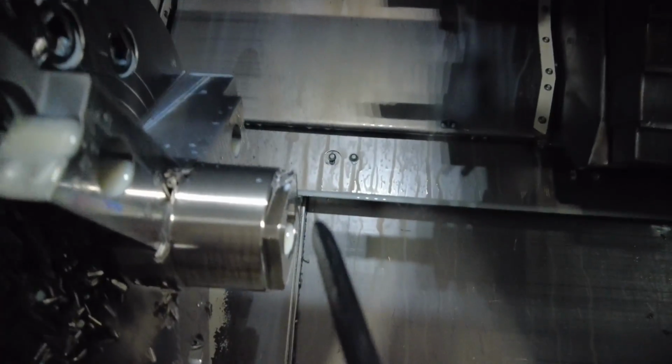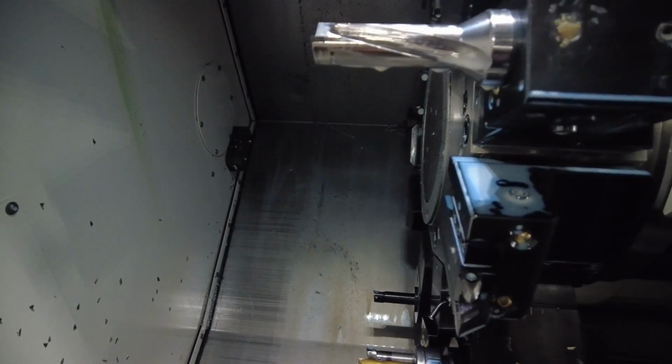So what this machine will do, it's going to take the 0 of the part, go up, and retract to the longest tool plus whatever additional default is set by the machine, before it rotates the tool and picks another tool to come back and continue machining. So that's all that is. It's a safety kind of feature.